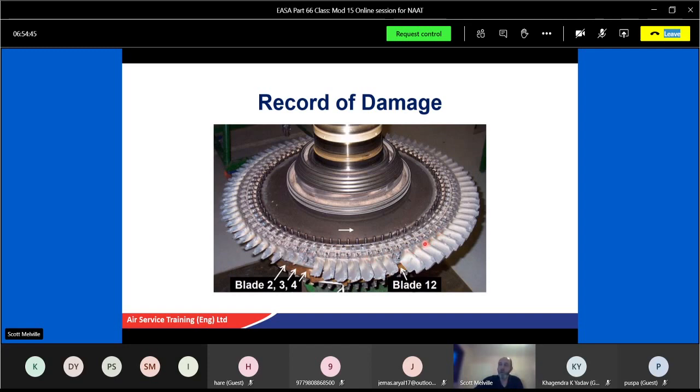Looking at that colour there, in my experience, that's the standard colour you come across. But certainly something's hit it. Maybe something's come through and actually hit the turbine blades, taken it out, and gone around the inside. There may be enough stress on these ones to break them off, or it could be a faulty blade from when it was made. Again, without the information, I can't really say, but certainly something's hit it, or maybe this one's come off and trashed the blades and taken some out with it.